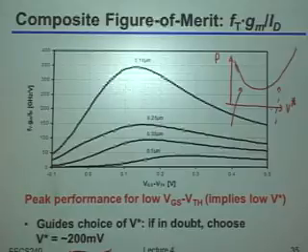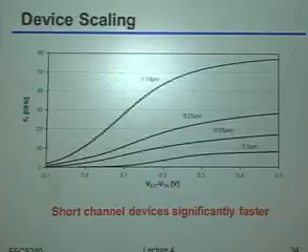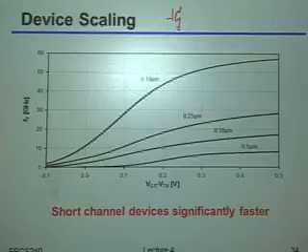Okay. So by the way, when I'm moving in this direction, as you decrease the V star, what happens to the FT of the device? Does it go up or does it go down? It goes down, right? So as the FT of your device goes down, let's draw a picture over here since I have a little more space. I'm just going to draw the simplest transistor amplifier. I'm not even going to draw the bias current source because I'm lazy and I don't have enough space on the top of the slide here.